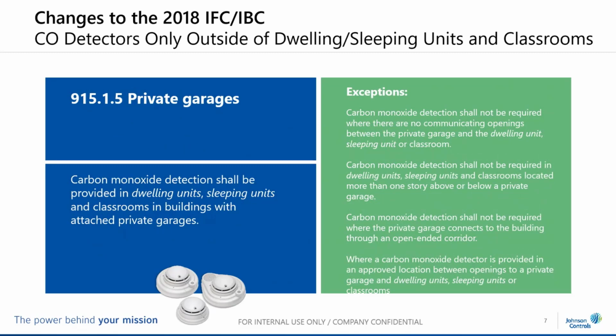In garages, people kind of forget about carbon monoxide coming from vehicles. A vehicle either running for a long time, maybe idling, can build up CO over time, and we're going to discuss later on how concentration levels affect us. But it could be a vehicle that's malfunctioning, or somebody pulls into a garage and lets it run. So when we look at these attached private garages, the term detection again was replaced with detector, which means only CO detectors are allowed in these approved locations within private garages and dwelling units.